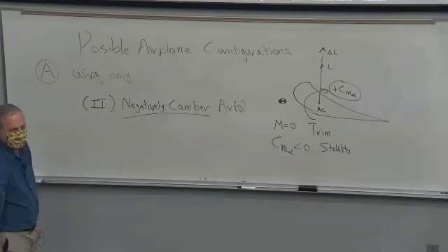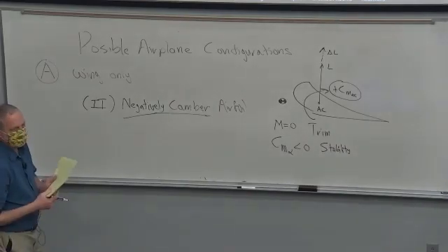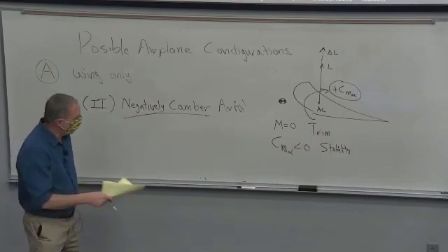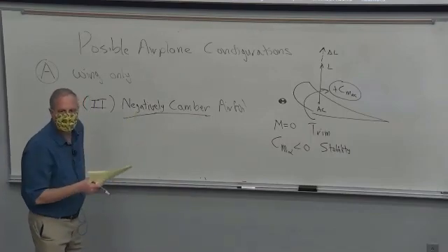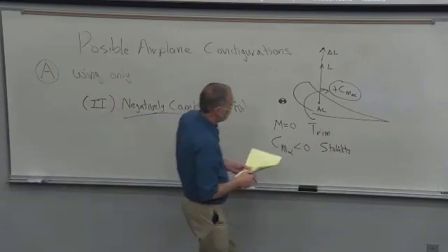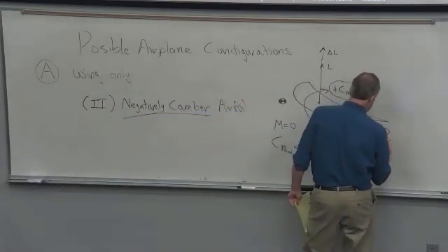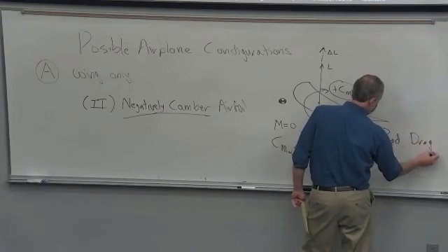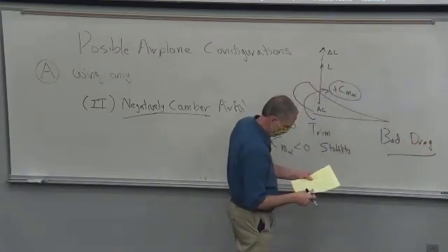So that works, but an airfoil cambered like that has bad drag characteristics. It produces lift, but you have to tilt it up a lot to get lift, and so you get a lot of drag. So you could do this. It just doesn't always work that great.